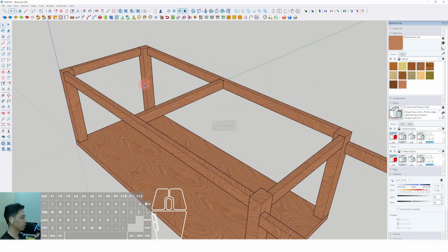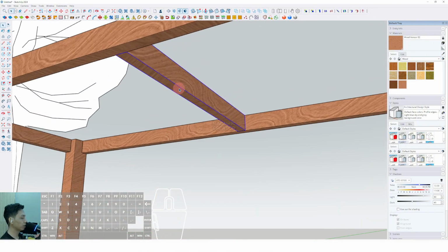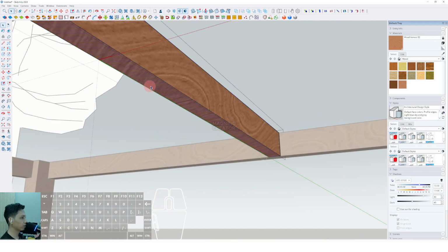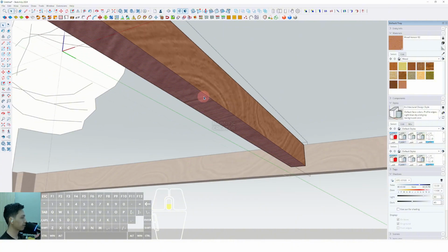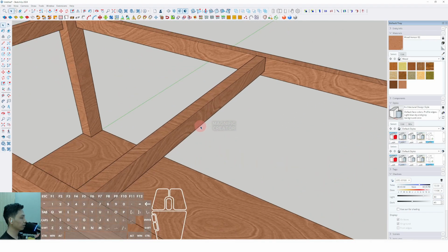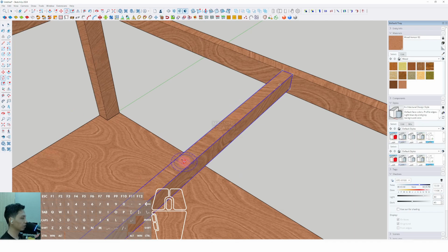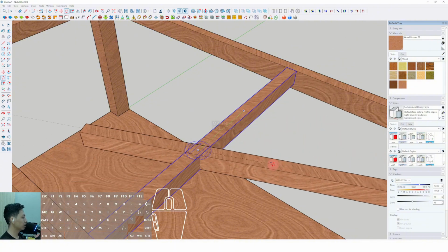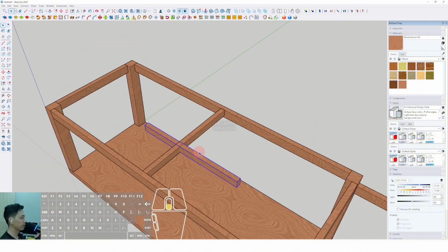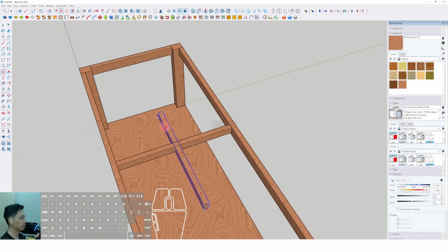And also we can make another horizontal frame in here, or we can make it thinner. You can triple click the surface, push pull, click this surface again just a little bit, around 10 millimeter. Okay, then we can click again and select rotate, tap control, click this surface and click any surface again and type 90 degrees with this direction. Okay, then we can click move, click this midpoint and place it to this midpoint.